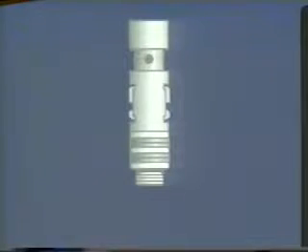The design and function of the X lock is a little more complicated than the S lock. The position of the keys on the lock mandrel are controlled by double-acting springs. These springs either hold the keys retracted into the key retainer while the lock is being run in the well, or they move the keys out to locate the nipple once the desired nipple has been reached. The key positions of the lock mandrel are controlled by the running tool, and the running tool used to run the X-lock is the Type X running tool.